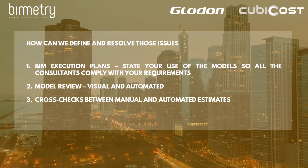So if the models are going to be used for quantity surveying, they might add additional modeling requirements, such as not having duplicating geometry, such as modeling everything in the right category, such as including the cost that is related to the object specifications. All these can be included in the early BIM execution plan, and the designers from very early on work towards BIM models that are good for quantity extraction, basically.